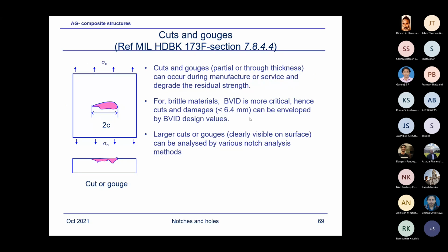Anyway. Now, suppose, instead of through thickness cracks, there are situations where you might have cuts, gouges, and how do you determine or validate this? It all depends on how much is the notch, say depth, this is scratch or gouge, and the length. Suppose this is pretty deep, almost like 40-50% of thickness, you would consider the damage, even though it's not a through thickness crack, you will idealize it with a through thickness crack.